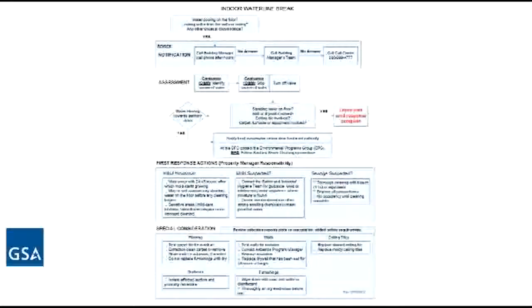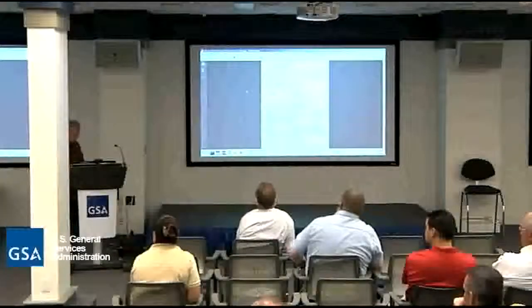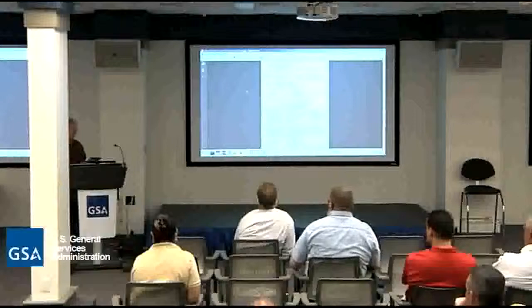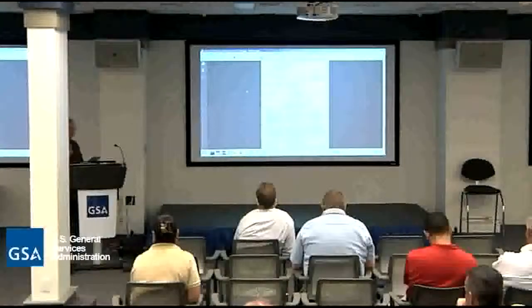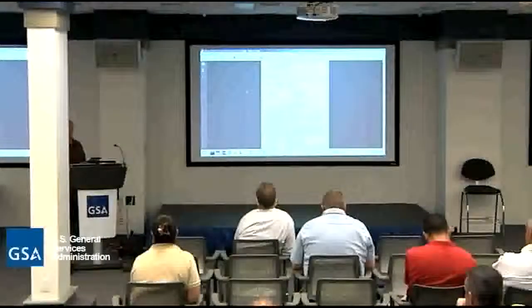Prior to jumping in and doing the remediation of the situation, check the asbestos books. Check before you rip in or drill the holes to dry out a stud wall. You may have to be doing some of this work in containment if we've got asbestos in the wallboard. Again, start drying out and cleaning up the area as soon as you can.